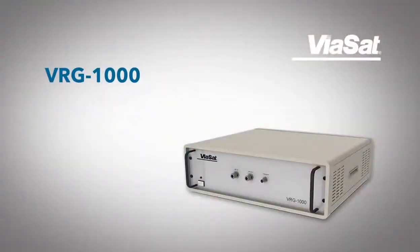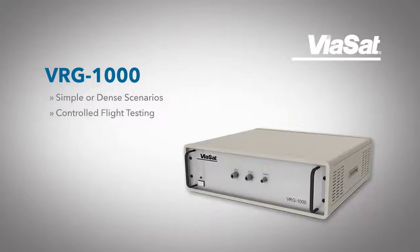Some of the uses of the VRG would be just simple interrogation and transpond testing, dense interrogation and transpond testing where you have more than one radio being generated. We can do controlled flight testing to simulate a flight test prior to the test or to determine anomalies that are discovered after the flight test. We can do interference analysis where we can set up an environment and see if your environment will interfere with the civil aviation radios. We can also do AIM certification testing and much more. The VRG-1000 provides a realistic flight test in your laboratory.